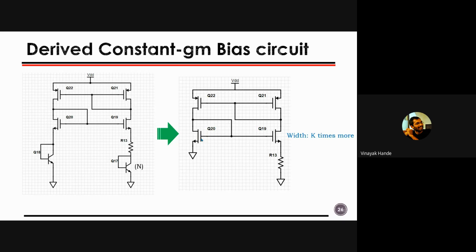Fine. And one more thing I wanted to tell before leaving this slide is that the connections of the 4 transistors, particularly the gate source connection, if you reverse that connection, the circuit will not work at all, because the feedback action will not be complete.